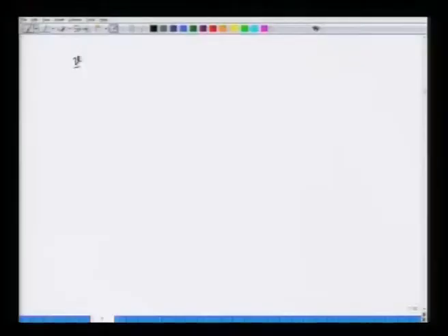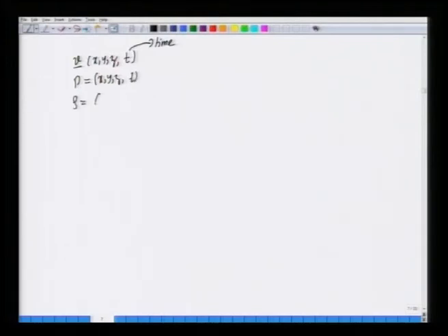So, once you use that framework, the continuum framework, we will define velocity as a function of all the 3 coordinates in the fluid in the coordinate system, and time, pressure as a function of all the 3 coordinates and time, and density as a function of smooth functions of all the 3 coordinates and time. These are called fields, continuum fields. Okay. So, these go by the name of fields. And we assume that they all can be differentiated easily, they are differentiable, smooth and continuous.